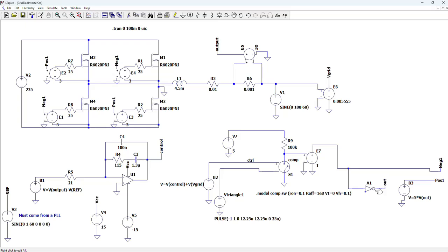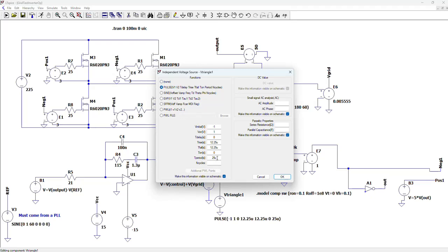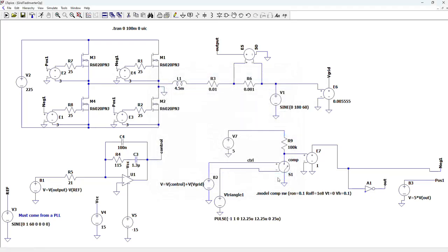Here's the inverter part just to produce the positive and negative pulses for the H-bridge converter. If you go back to the inverter, you can check where these signals are applied. The positive pulses and also the negative pulses are appropriately applied to the MOSFETs. So my triangular is from -1 to 1. My frequency is 40 kilohertz, so I have here the period for this switching frequency. And talking about the controller, I just put here the variables that I computed in that script.